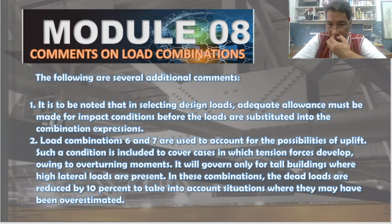What do we mean by dead loads reduced by 10%? Dead loads are to be multiplied by 0.9. That's why it is reduced by 10%. Why? To account for situations where they may have been overestimated, because we want to maximize the effect of wind and earthquake for tall buildings.